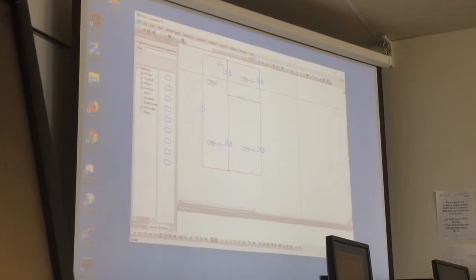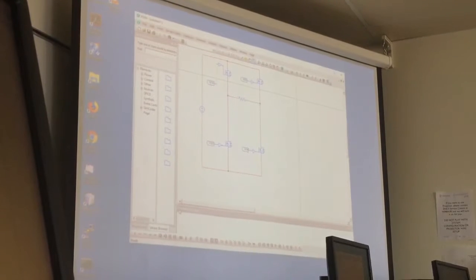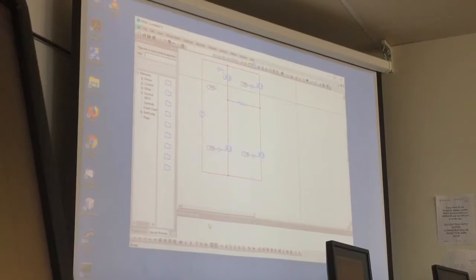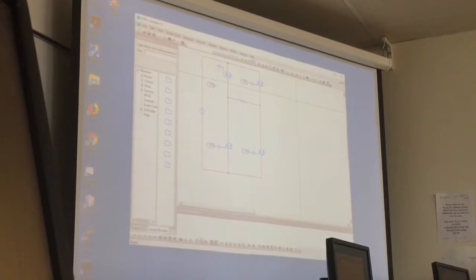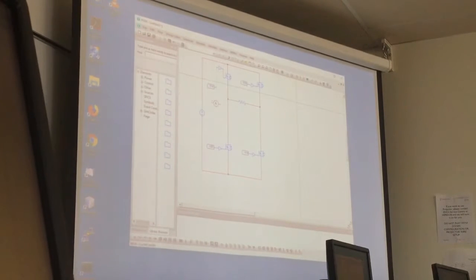So we have our converter here. Now let's say we want to see the currents or the voltage. We need to find the probes for this. We have three probes. We have the current probe, which is placed here, can you see? As you guys might be aware, we just need to place this in series with the element that we want to see the current, okay?